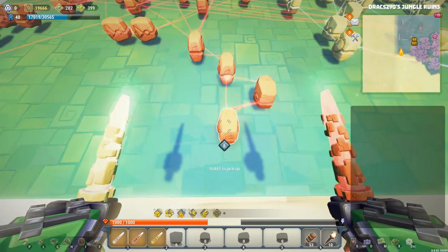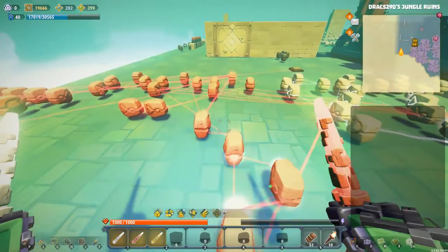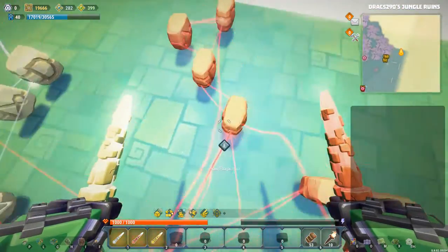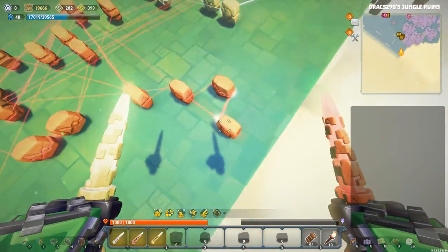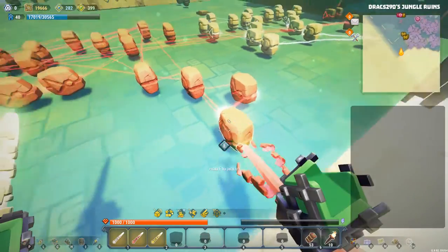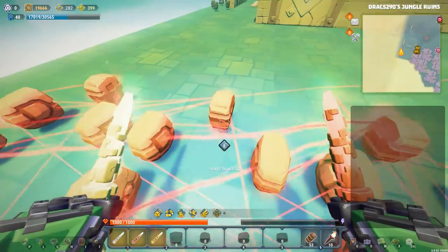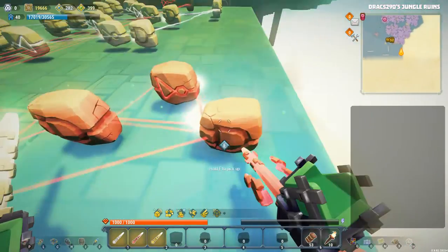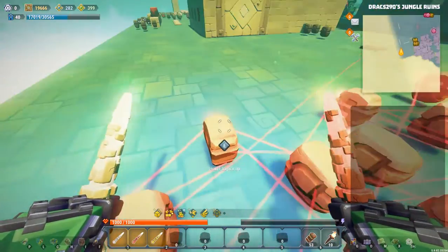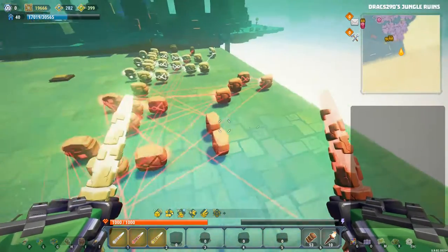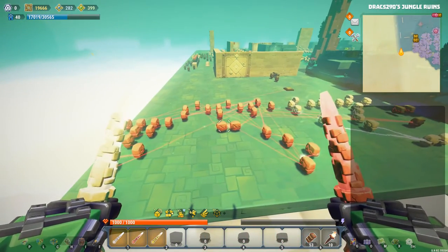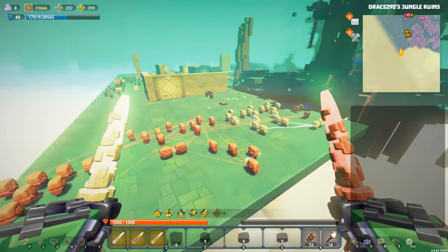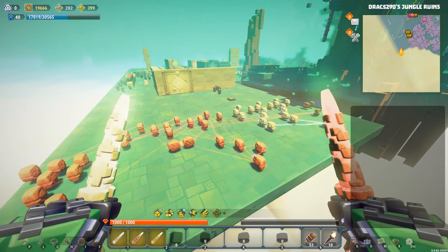So to finalize the circuit, what we're going to do is run this guy up and have that turn on the first latch and then turn off the other 2 latches. So it's basically going to be a system reset button. When that all happens, it's going to turn on the first one and off the last two. So that's exactly what I'm doing. I'm just running it up here, putting it on there and turning them off. So that's just going to be a quick little pulse that goes through the circuit and just resets it back to the base state, so that will sit there and it will be fine.